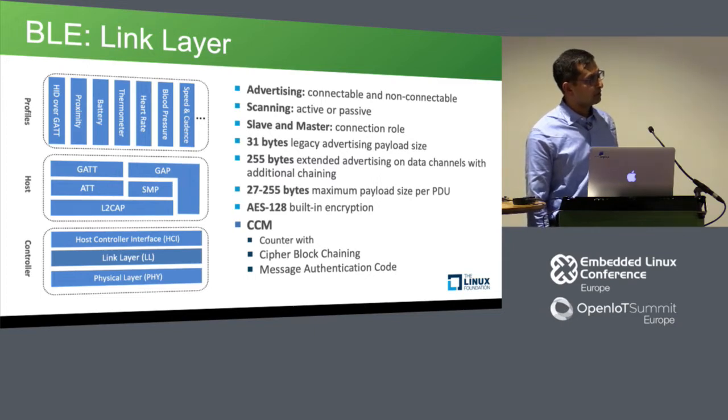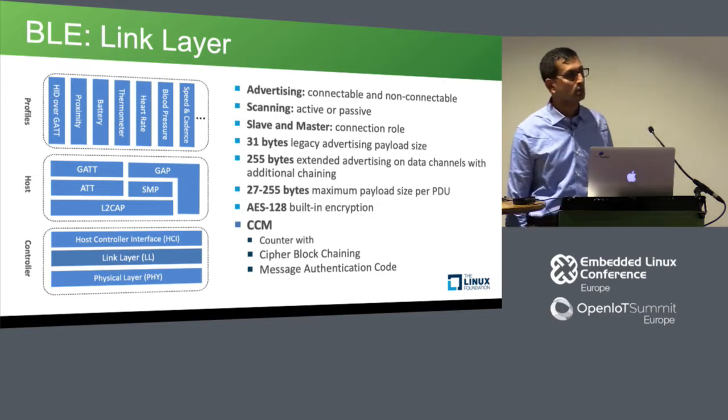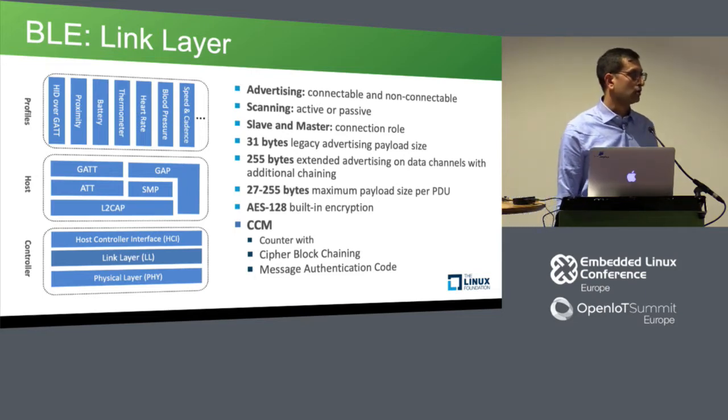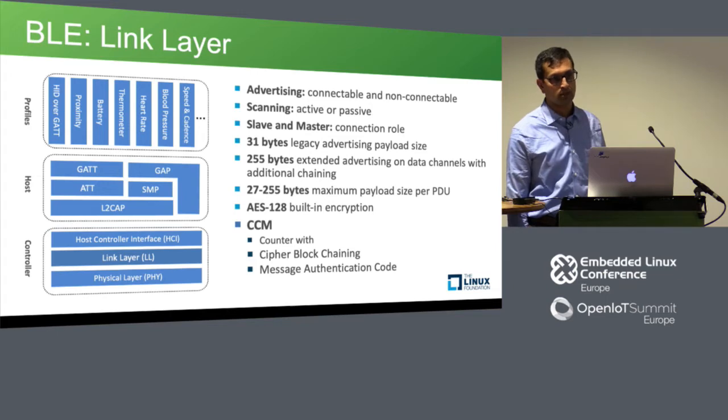On the data channels, the legacy PDU size was 27 bytes. With 4.2, you can actually have 255 byte payloads, PDU lengths, and BLE has built-in AES-128 with CCM. So all your data exchanged would be encrypted.